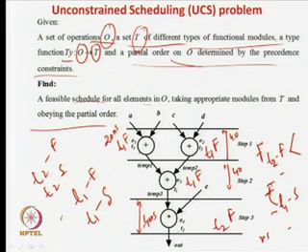So, there is no use of putting a very fast adder over here, because the fast adder's area will be higher than a slow adder's, and even the power of the slow adder will be less than that of the fast adder. Here I am putting in more area and more power, computing everything in 20 nanoseconds, but I still have to wait another 20 nanoseconds, because the time period is 40 nanoseconds and it is determined by the slowest element of the block, which is the multiplier.